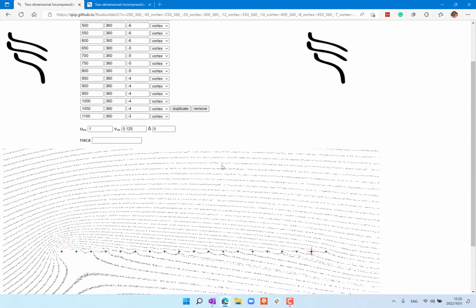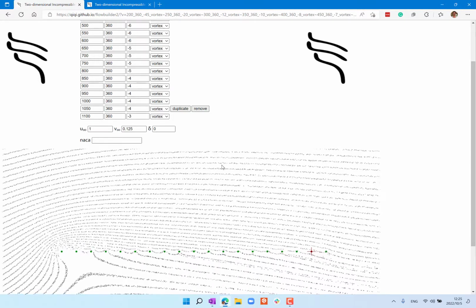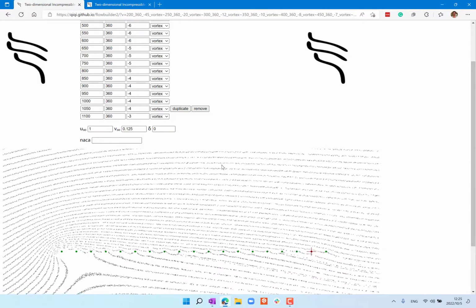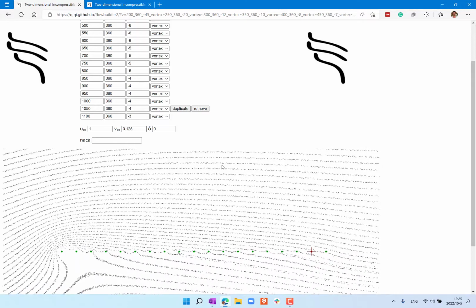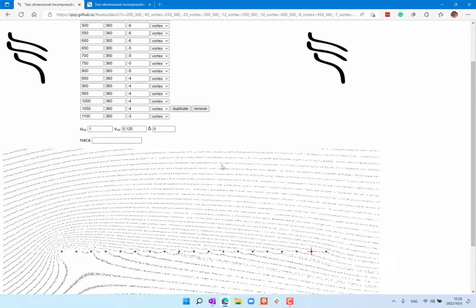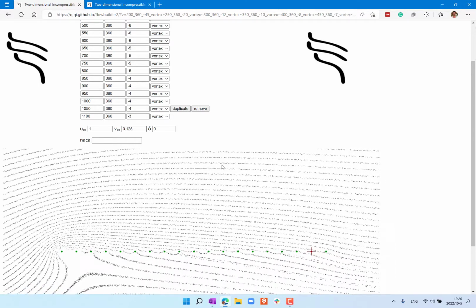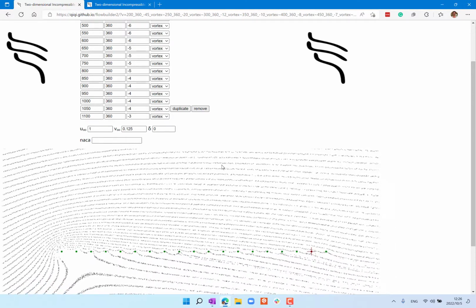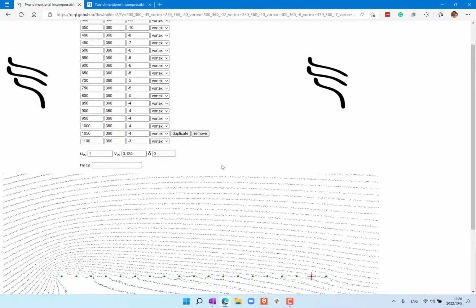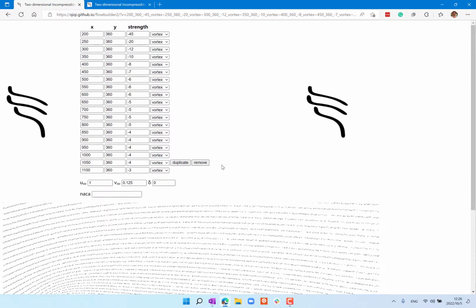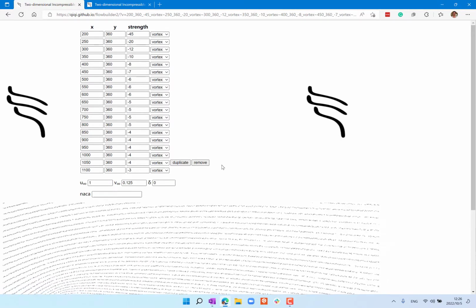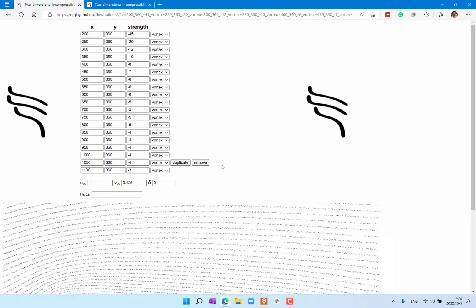So the flow actually goes across the airfoil at that V infinity. And to balance that, you add exactly the same distribution of vortices on the airfoil to simulate the increment in angle of attack, not just for a symmetric airfoil, but for any airfoil. So this function is non-trivial to work out, but is extremely important. I mean, that's the thing that matters in the aerodynamics of airfoils.